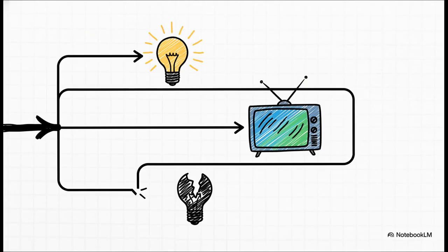And this is the absolute magic behind your home's wiring. In parallel, the voltage is the exact same across all elements, while the currents adjust themselves individually for each branch. And the best part? A break in one branch doesn't affect the others at all. You can turn off your TV without plunging your whole living room into total darkness.